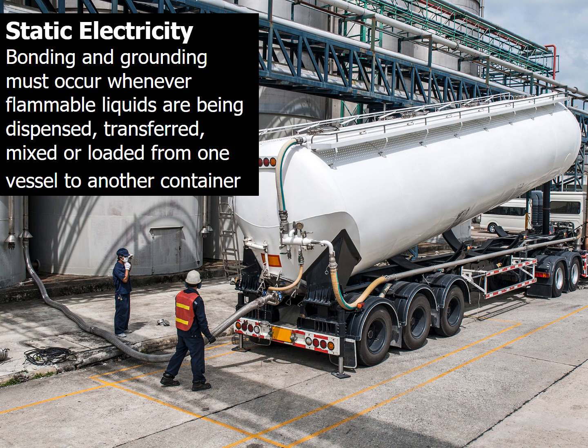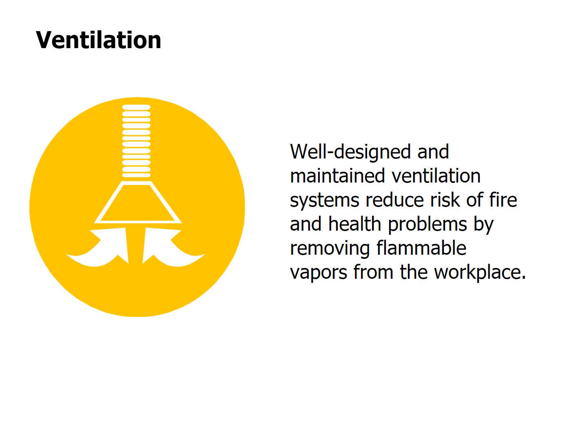To dissipate static electricity, the container receiving the liquid must be in contact with the ground and not insulated from contact with the ground. Bonding and grounding must occur whenever flammable liquids are being dispensed, transferred, mixed, or loaded from one vessel to another container. Well-designed and maintained ventilation systems reduce risk of fire and health problems by removing flammable vapors from the workplace.